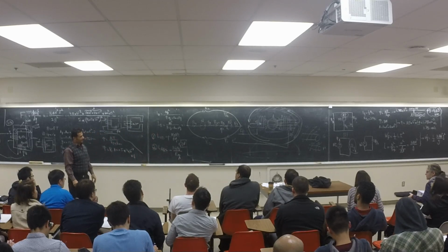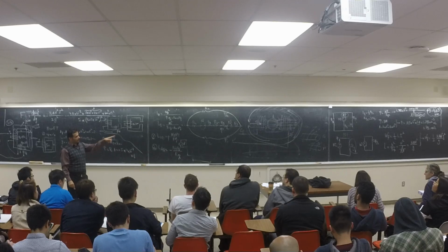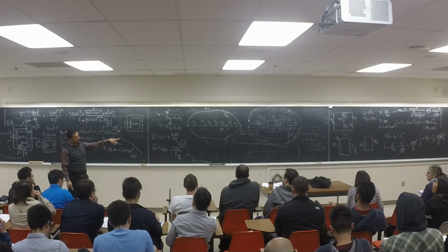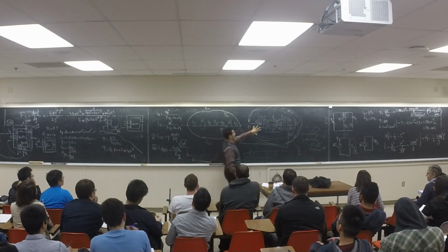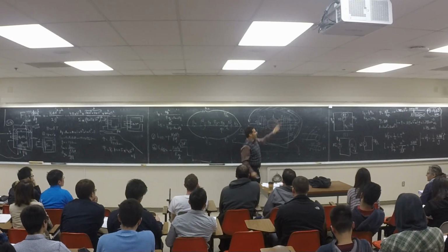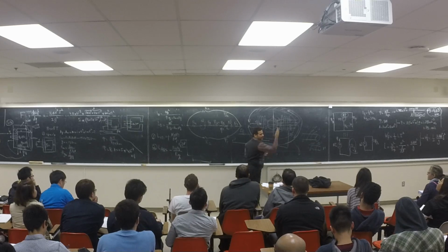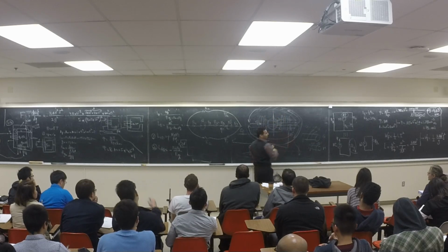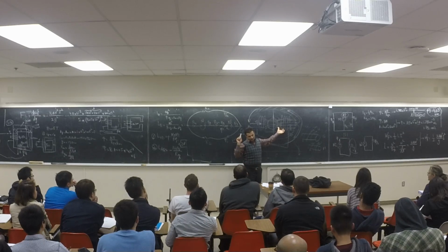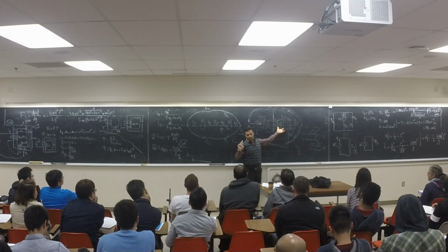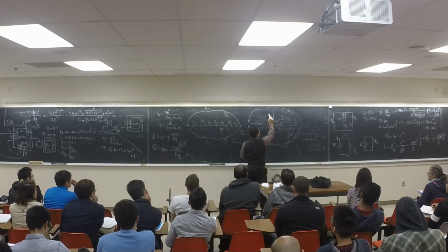This circuit is easy because the rotor is cylindrical. It doesn't matter what the position of the rotor is. Let's say this is the axis, and the rotor is rotating. All the time the air gap is constant because it is a cylinder, right? There are some machines they call solid pole machines. The rotor is like this.